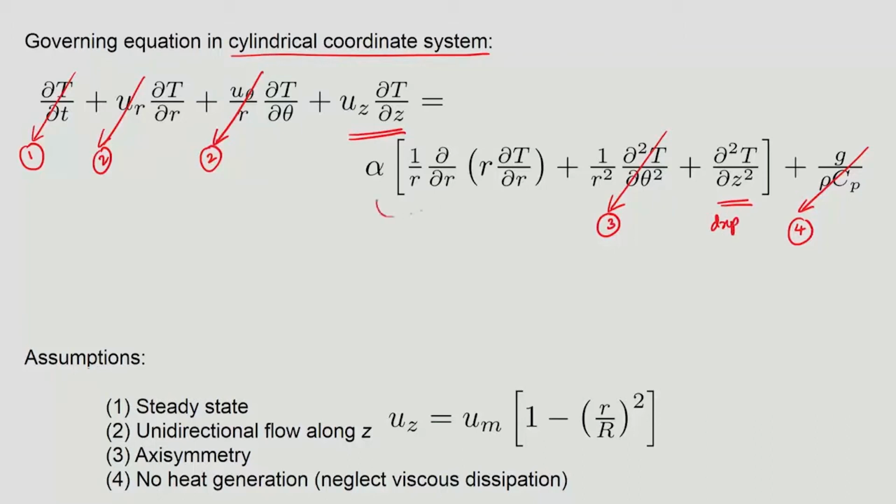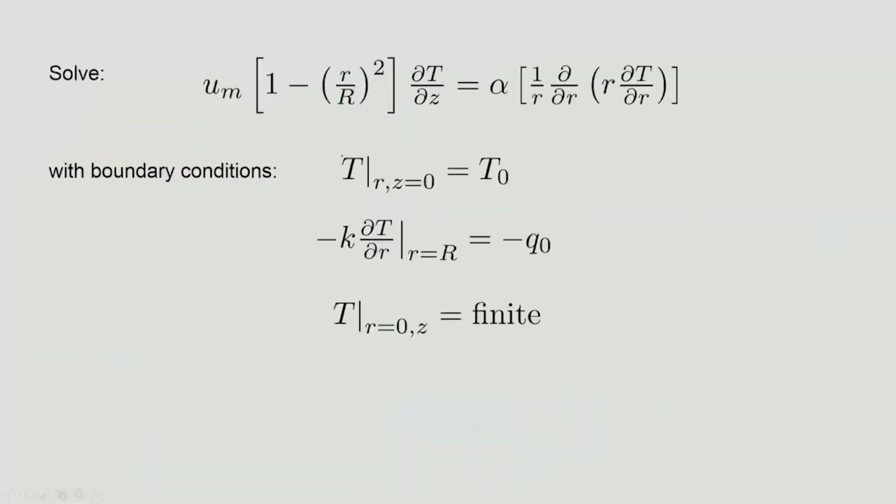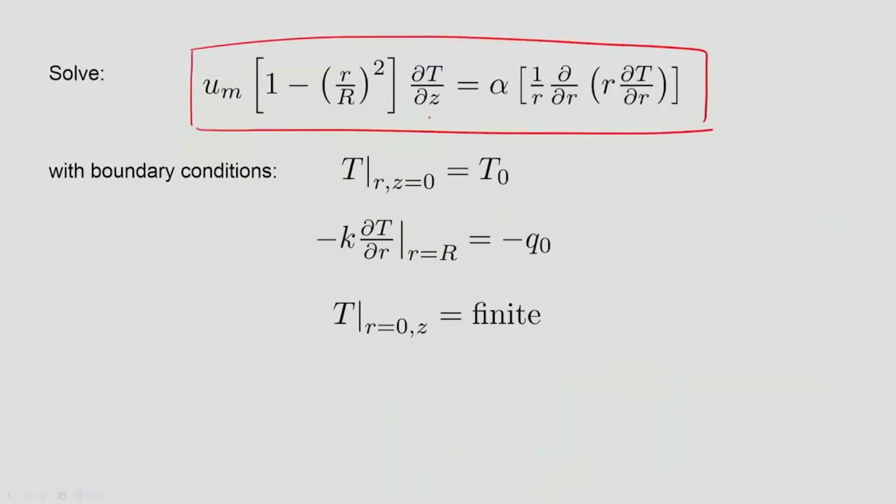So, which then leaves us with these terms, and we have the flow decided already, the functional form, which is what we would actually introduce into this. Okay. So, then the governing equation would come out to be here in this manner. So, you would see that there is a ∂T/∂Z term and then ∂T/∂R term. So, that we actually seek temperature as a function of R and Z. Okay. So, that is what we are wanting.